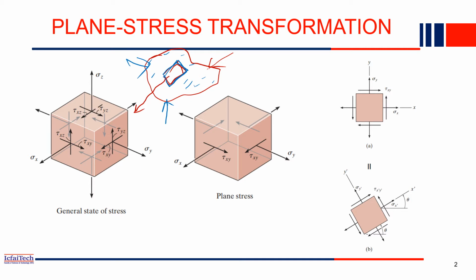And these two are the shear forces, which are along the plane. So each plane has two shear forces, that is tau in two directions, and one normal force, that is sigma y. On each face all three forces are exposed. This is the general state of stress.